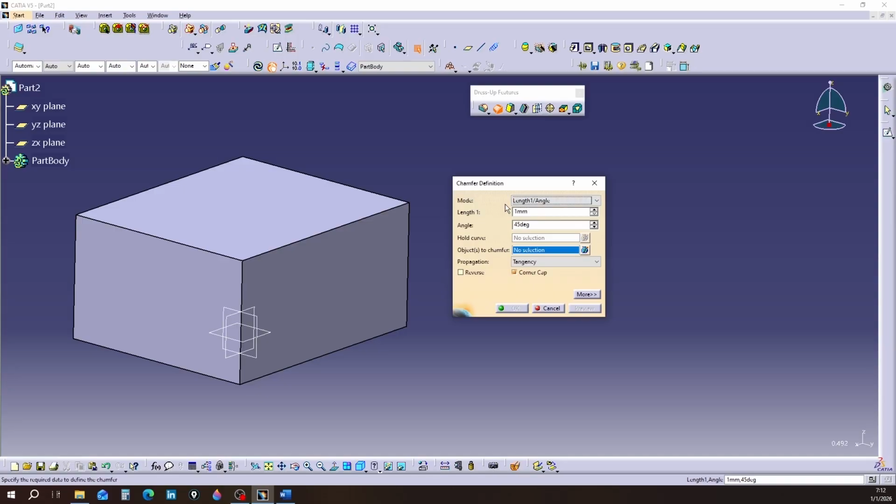First, pay attention to this question. In chamfering, is the edge important or the surface? Chamfer is inherently an edge-oriented operation, but its result is entirely dependent on the side surfaces of the selected edge. From a selection point of view, we select the edge. The chamfer is defined on the edge. A chamfer without an edge has no meaning at all.